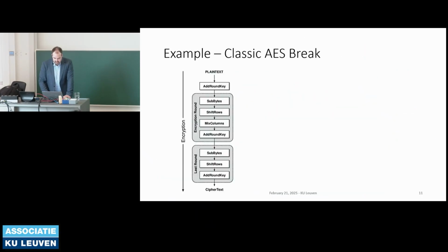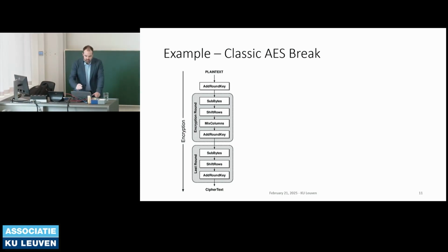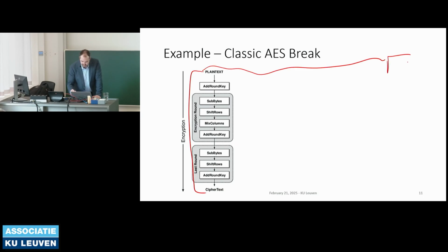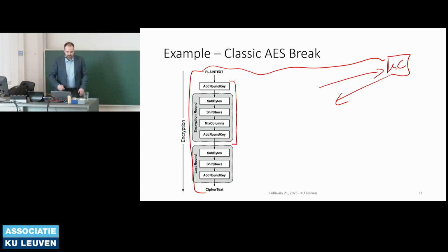If I have AES running, what I'm going to be doing is programming this AES algorithm into my little microcontroller on the board here, and then I'm going to send data to the microcontroller. It's going to encrypt it and send it back to me. It's going to run the AES algorithm, which is shown here. What I want to point out is that we're going to see this structure in our power traces. So we have some different unique steps.